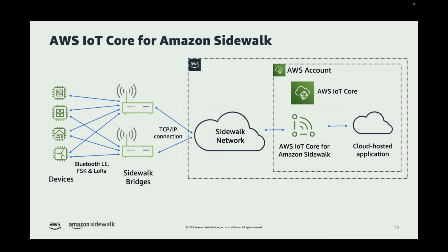I've seen some questions pop up in the chat. This is not just a beaconing kind of technology. Devices do beacon for a connection. They have to get an active connection from a gateway before they can actually send a message. But the neat thing about this is that the device is gateway agnostic. The device can start beaconing, and then any bridge within range will make that connection and offload the data. The device can go back to sleep, or it can maintain the connection if it likes.